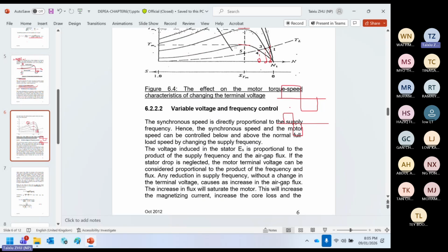The lower one, right? Yeah, because of the frequency. For example, the period here, now 50 hertz, right, is 20 milliseconds. I'm talking about 50 hertz. Yeah, but here you have 10 milliseconds only. So what is the fundamental frequency here? This one actually is 100 hertz. Yeah, this one is 50 hertz. So you can tell actually this narrower waveform can drive your motor to run faster, because this frequency is 100, this frequency is 50.